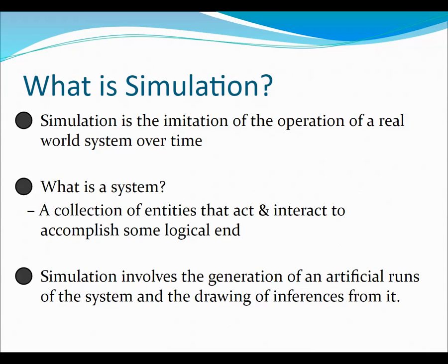It's a very typical project that a consultant company might undertake: build the model for the existing condition, build a roundabout into that model, and then do the analysis before and after. So look at those conditions. What you're doing is creating a replica of the system and then running the runs through it. And obviously there is stochasticity, which we will come to.